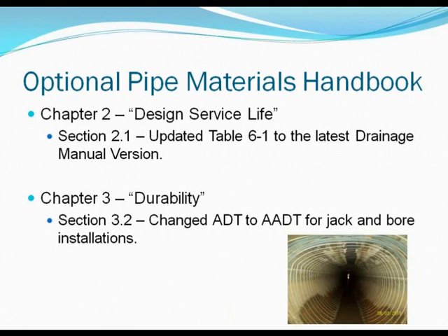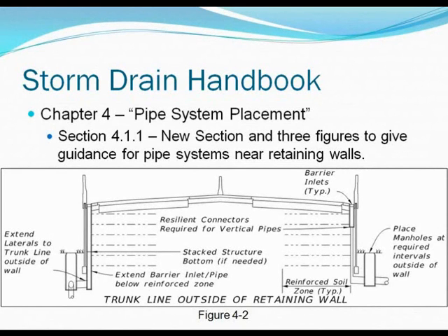We also have a drawing in there that you'll see, I think it's the last one back, of deep inlets. Deep inlets are preferred over, say, a system where pipes are running through the strap zone. These inlets are stacked and they're put piece by piece, and they're reasonably easy to clean out. One of the reasons we don't like pipe immediately adjacent to the MSE walls is if there ever is a severe problem, it's very hard to get to them.